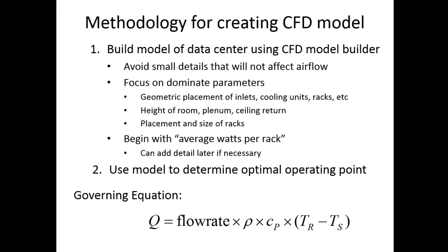You can always dial these models in tight later. It's a great thing about a model. You can increase its fidelity over time if you want. But it's the big things you want to get correct first, like placement of inlets, outlets, where the racks are, placement, number of tiles, percent area open for the tiles, height of the room, general big things.